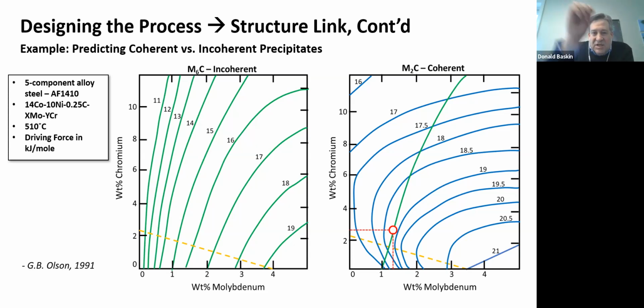So some of that FCC austenite that existed at the high temperature, sometimes that doesn't completely turn to martensite. Sometimes you're left with some of the austenite, and what happens is when a crack hits that area, the energy associated with the crack tip can then transform that austenite to martensite in situ as the crack hits it. And because there's a volume change associated with that, the martensite actually has a higher volume than the austenite atomic cubic cell. What that does is it clamps down on the crack tip, and you can effectively shield the crack tip and increase the toughness of the material.